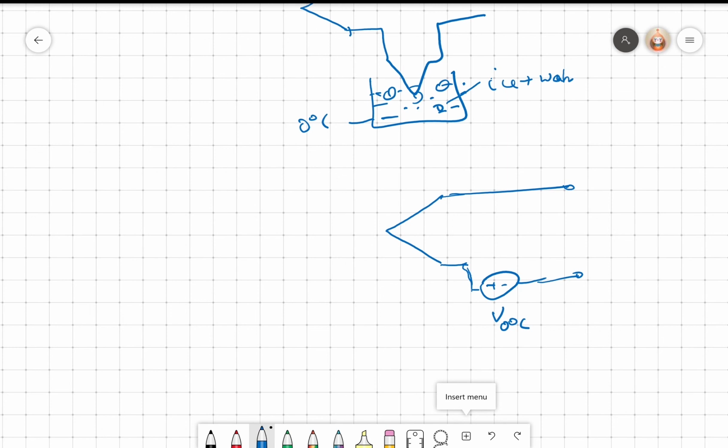So we look at the recap. We have learnt about the thermocouples. There are different types of thermocouples depending upon the materials A and B chosen. They are all given an alphabet name. J is iron constantan, K, E, T, R, S, C, B. There are different types.